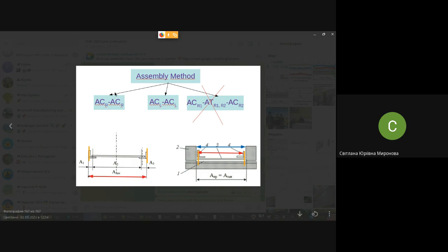What about the CFH hole? What do we understand as a CFH hole? CFH hole, coordinate fixing hole, or BH hole, base hole. Practically it's the same. What is the difference? We'll explain in a minute. CFH hole or BH hole, from the viewpoint of the designer, is not a necessary hole. It has no function in the aircraft during aircraft functioning, during aircraft operating. It's not necessary. It's an extra hole. And such holes appear in the structure by demands of manufacturing engineers, by demands of technologists.